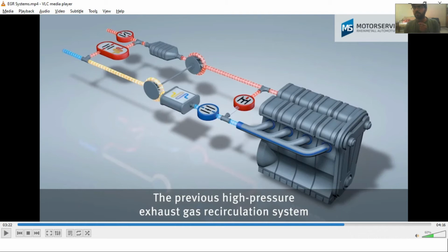But when we are talking about the diesel particulate traps, which we will discuss later in this video, they usually require higher temperatures, around 600 to 700 degrees Celsius. So in CI engines, the bypass will basically provide the emissions to the diesel particulate trap at higher temperatures.